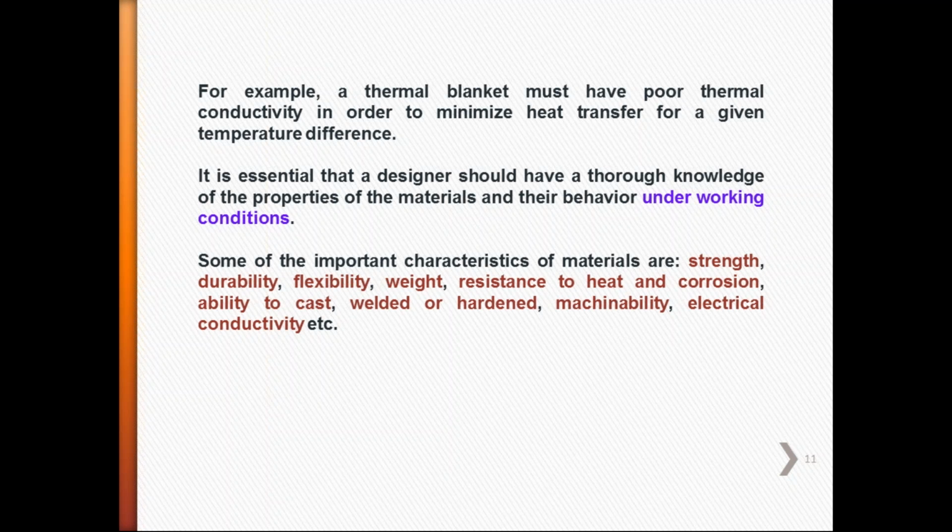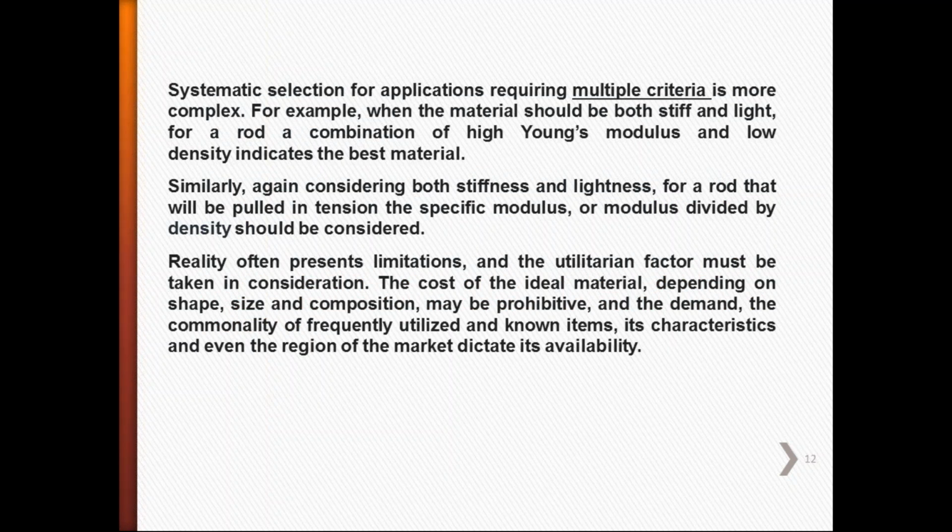It is essential that a designer should have a thorough knowledge of the properties of the materials and their behavior under working conditions. Some of the important characteristics of materials are strength, durability, flexibility, weight, resistance to heat and corrosion, ability to cast, welded or hardened, machinability, electrical conductivity, etc. Systematic selection for applications requiring multiple criteria is more complex.